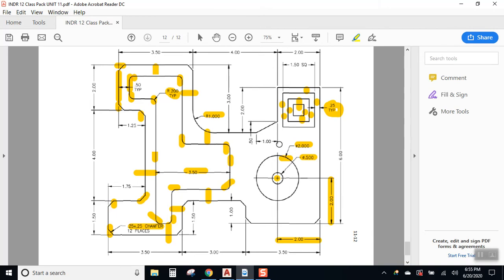And then the last thing is we've got this little odd angle. Now, I don't tell you what angle it is. I just tell you that it has a rise of 0.5 and a run of 1. So this is a chamfer. And I know it doesn't look like a beautiful, perfect 45 degree chamfer like these, but it's still a chamfer. It's just that this one has 2 distances. So maybe 1 inch could be distance 1, and 1/2 inch could be distance 2, and then when you click the corners here to make that chamfer, it will create that unequal chamfer that we're looking for.